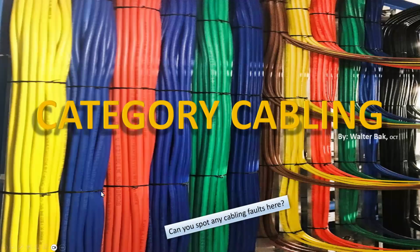All right. Now, within some companies, there's a hard rule of not using even zip ties with data cabling all across the board. All employees are not supposed to use zip ties with data cables. There are some companies that are strict about that. The problem with using zip ties and twisty things like this is that you're deforming the cable. You're making micro bends, and let me explain to you what a micro bend is.